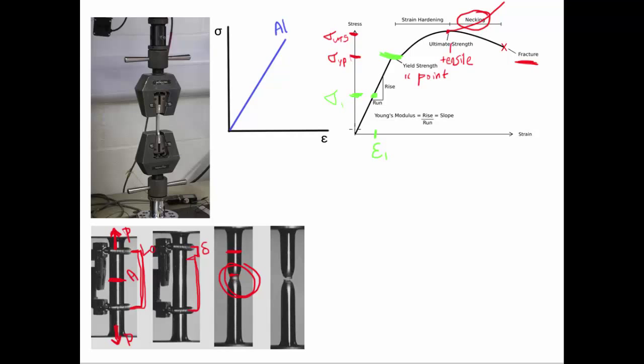So for most materials, they will deform elastically for a while, and then beyond some point, they will deform plastically. A few materials will break before they ever start to deform plastically. That is, they are elastic up to the end, up to the fracture point, and for those materials, there is no curved portion of their graph. The graph is completely linear the entire time. An example is glass. It might seem difficult to believe that if you pulled on glass it would stretch, but it actually does. It stretches a little bit. It stretches until pop, it breaks.